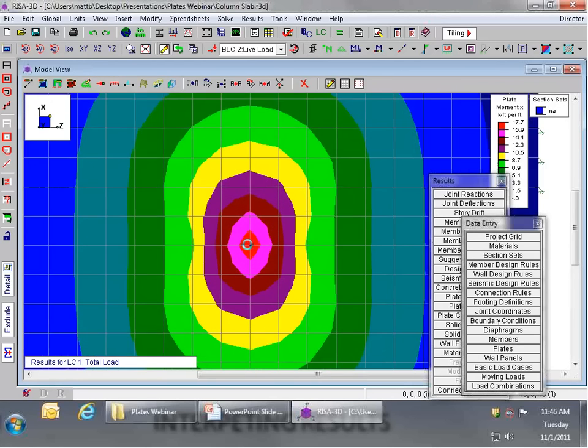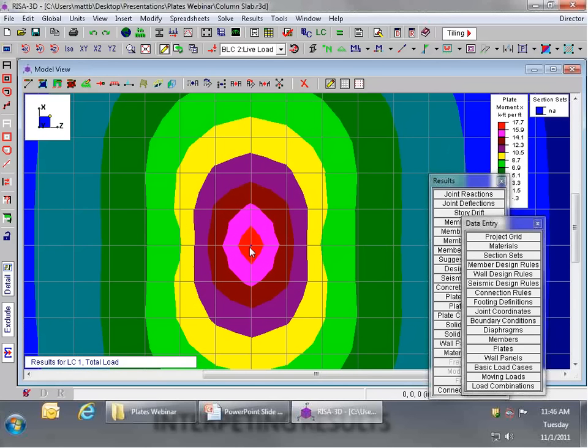And so what we're dealing with here is the fact that that 30 kip point load for that column actually comes down at a tiny little needle point right here in the middle of my slab. That's not terribly accurate. In reality, the panel zone of this column is going to sort of evenly distribute that load out, and what we care about more is the moment at the face of the column.